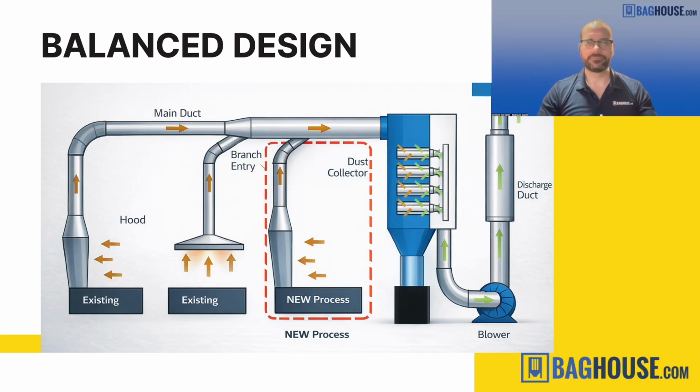And you continue this pattern all the way until you get to the last pickup before we go into the dust collector. By laying it out like this with your OEM, you're going to be able to see how we design the ductwork properly so that throughout the whole system, the air velocity is always the right speed, so you don't have material building up in the ductwork.